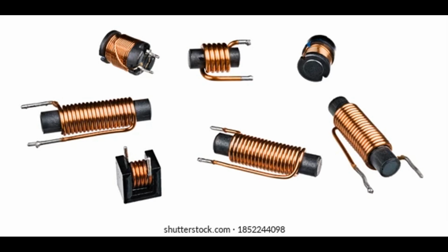2. Advantages of ferrite cores in reducing losses. A. High magnetic permeability. Efficiency. Ferrite cores have high magnetic permeability, which allows them to concentrate the magnetic flux more effectively. This results in higher inductance and improved efficiency because the core can store and transfer more energy with less magnetic field leakage.